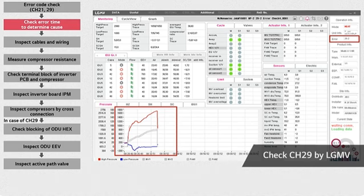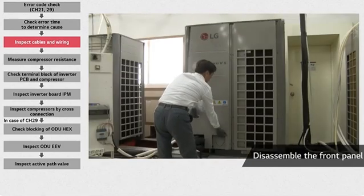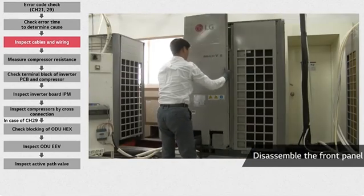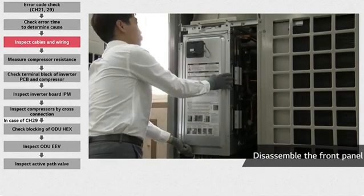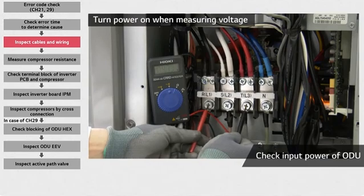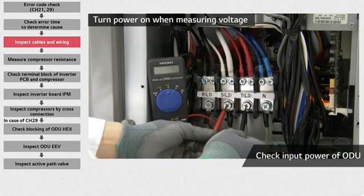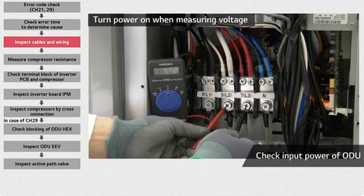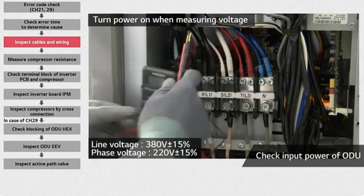For a more detailed explanation regarding this issue, please refer to the following steps. To carry out a closer inspection, start by disassembling the front panel of the outdoor unit. Then disassemble the control box cover of the outdoor unit. Their value should be 380 volts. And RN, SN, TN are the phase voltage. Their value should read 220 volts each. Check if the wires are tightly connected.